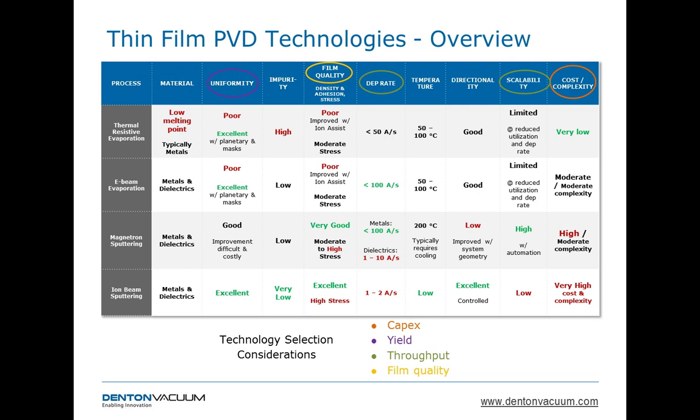For a laser diode with, let's just call them quote-unquote low technical requirements, meaning maybe a low power laser bar, we would have thermal evaporation for metallization layers. Although they are fairly cheap, they can be sufficient in a lot of cases. A slightly better technique, but slightly more expensive, would be e-beam evaporation, which gives you a broader range of available materials, slightly higher deposition rates, and possibly a little bit better film performance.